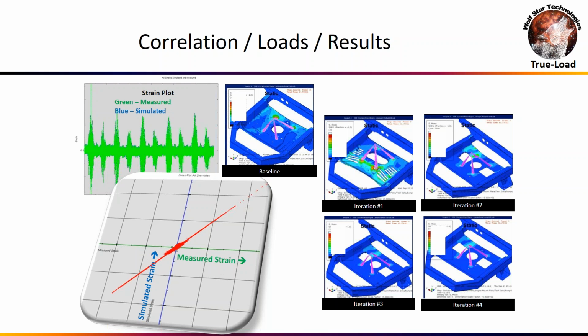They had their initial design that they ran through FEA first, and they had it on shaker test the day I was there talking to them about this, and they brought me to the lab to show me their first design iteration, and the part had failed in 12 hours in the lab. It's supposed to go 10,000 hours. So this part that you see here had failed in 12 hours, and I said, perfect.